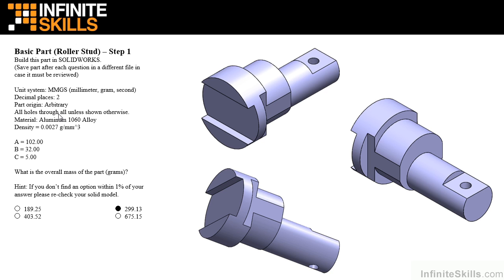We also have a note telling us all holes extend through the entire part unless otherwise shown. Looking at the pictorial views, we have one hole feature, and it does appear to extend all the way through the part. But we'll verify this when we read the drawing views.